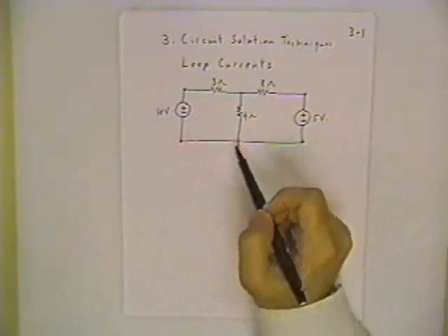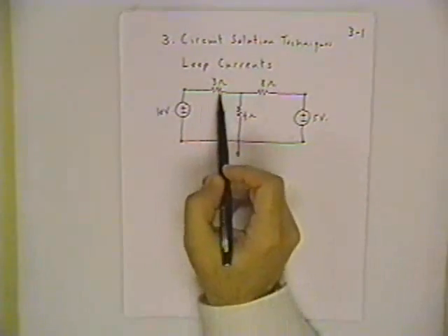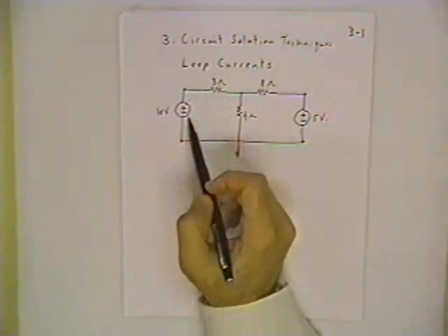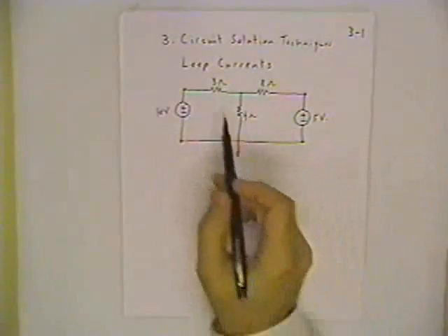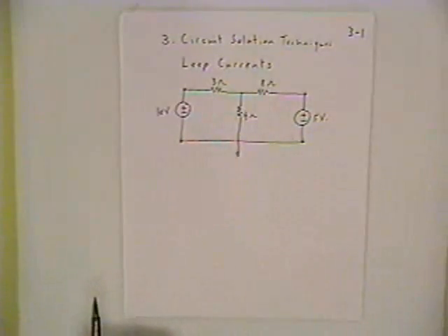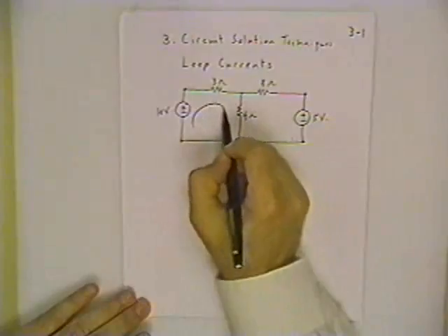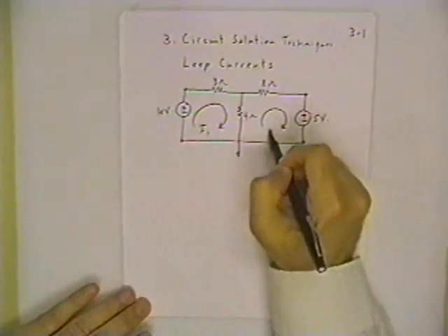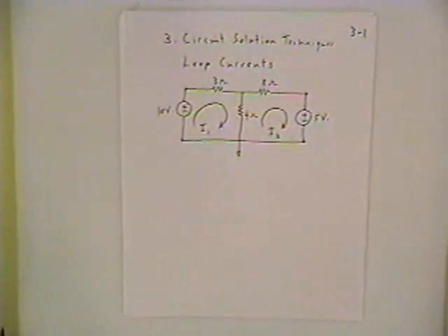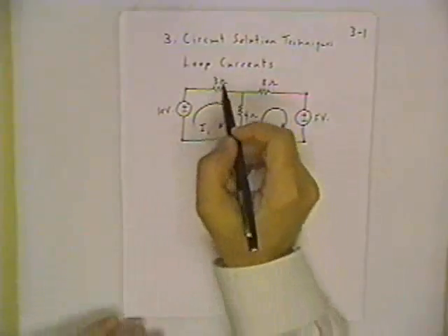As soon as we know those currents, Ohm's law tells us that we can calculate the voltages. And if we can figure out the current in this resistor, for instance, we'll automatically know the current going through this source because they're connected in series, and likewise for this combination. So some way or the other, we need to figure out the currents in these resistors. The loop current technique says, let's just assign a current to each of the loops in the circuit, and then write down the Kirchhoff voltage laws. Well, I'm going to use my technique of labeling the polarities of the resistors.